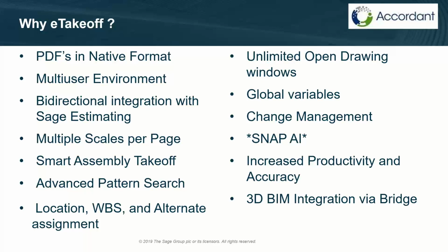Another of the features that eTakeoff has that many others do not is the multiple scales per page. You'll find this more frequently on your details page, where you have one set scale for a drawing on a portion of the page. Another portion of the page may have a different scale. eTakeoff will allow you to define different scales on that one page. Other applications kind of force you to copy that page, so you end up getting page after page after page.